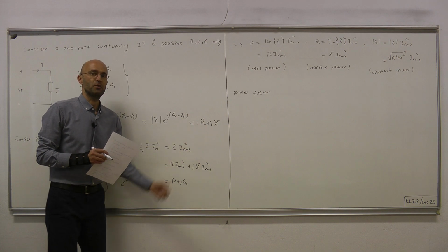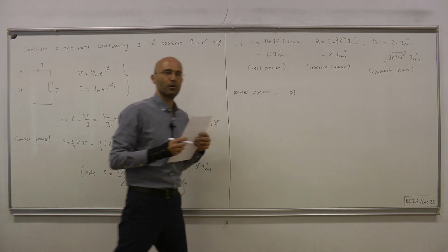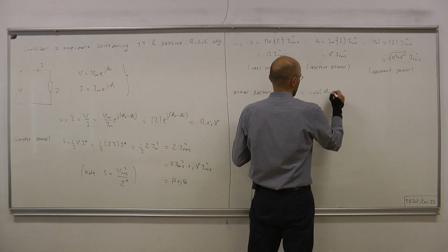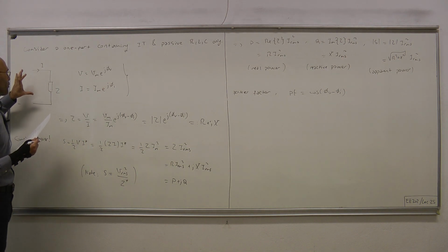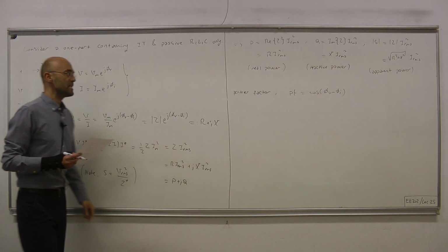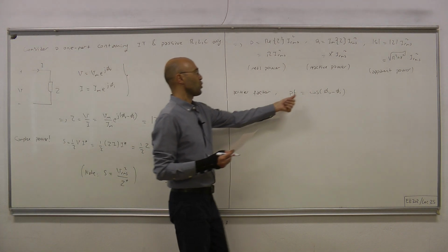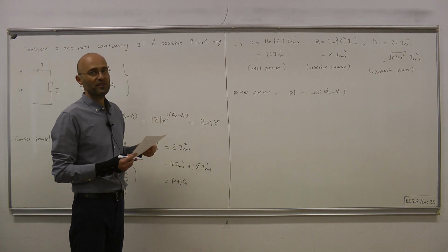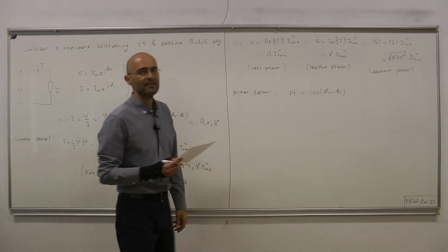this phase difference between voltage and current. So power factor, indicated by lowercase letters PF generally, is cosine of phi v minus phi I. So once again, the power factor for a one port is the cosine of the phase difference between the phase of the voltage and the phase of the current. Since it's cosine of something, it can at most take the value 1. And magnitude wise, the smallest that it can get is 0.